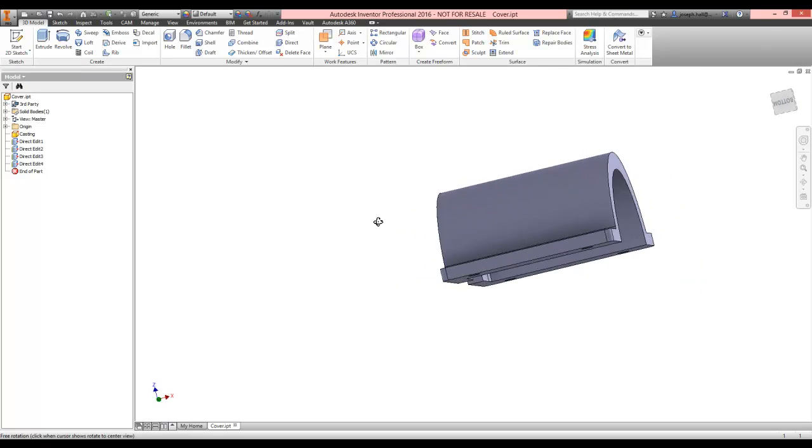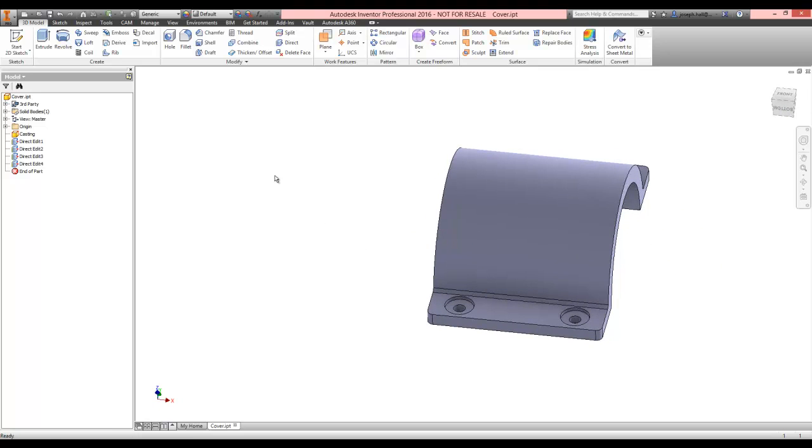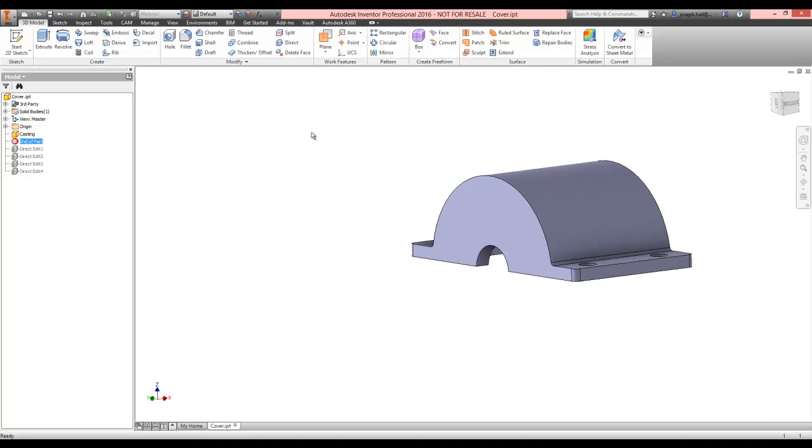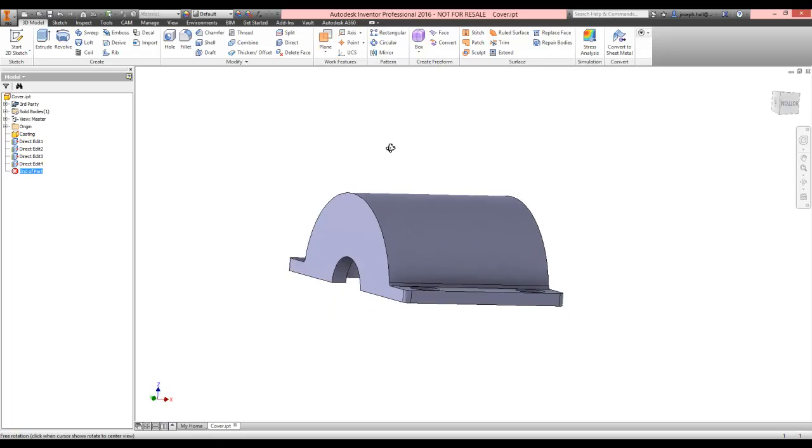It was imported geometry, it was just a standard CAD, standard CATIA model. There wasn't any history to this, so you can see if I go back before I do any of my direct edits, all this is an imported lump of something. It's a solid lump of stuff. There's no intelligence there. What I've now done, utilising direct editing, is put some of that intelligence in there.